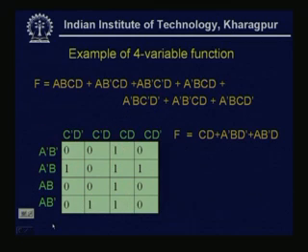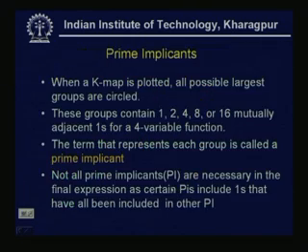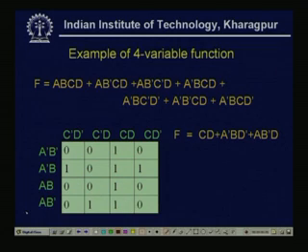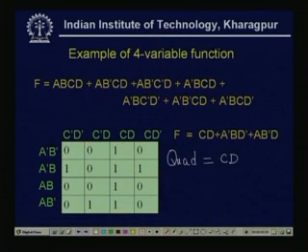Now, what will be the quad? See, this is from the K map, the quad will be simply the CD, because all the 4 columns exist, that means all combinations of AB exist, and that is why all complemented and uncomplemented literals will cancel each other. So, it will be simply the third column.